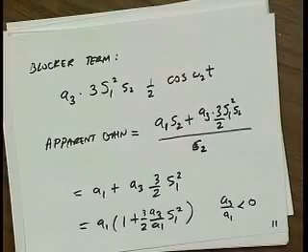Now, true, there is intermodulation distortion that we already took care of last lecture, right? You get intermodulation products. What we're seeing here is that even if you could filter out those intermodulation products, you're still going to experience less gain in your system. So this is not an intermodulation term. This is the term at omega 2, the desired frequency. So the gain of our system is apparently dropped because of this jammer.